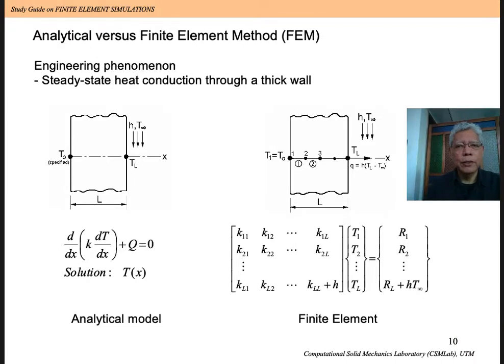This slide illustrates the solution approach to heat conduction problem by the finite element method. Analytical solution or exact solution is known for the given boundary condition. And finite element method discretizes the solution domain into finite number of nodes across the thickness. And a linear set of algebraic equations are then assembled for solving the unknown nodal temperatures.